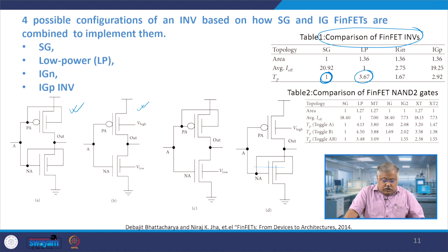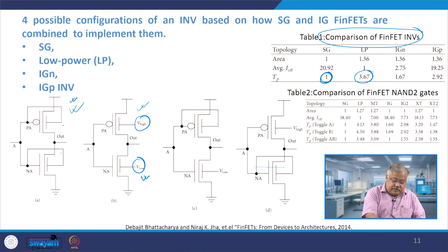Now, if you look carefully here, this is basically a single gate inverter, and this is also an inverter here, and I am assuming that the substrate potential has been given. So, the substrate bias effect is there. Here there is no substrate bias because you have shorted the output and input here, right.